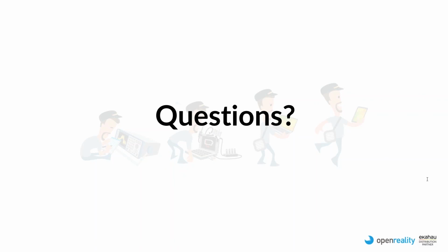But yes, please. There was a great first question from Iqbal, which is all to do with versions of surveys. So he's basically asking, can we still load older surveys into version 10, and will we still get the same integrity of results? Okay, so the answer is yes, you can open older project files in version 10. You can't go the other way. So you cannot open a project file saved by version 10 with Ekahau Site Survey version 9. And the data will be unchanged.